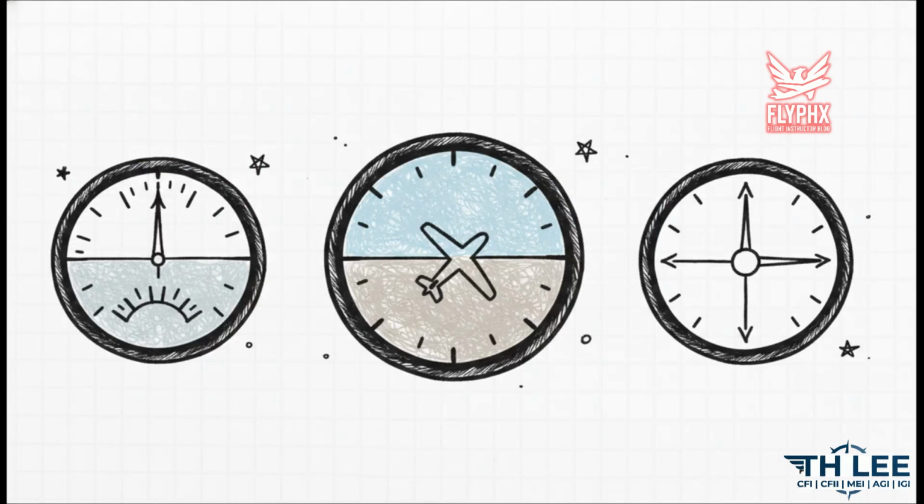Regardless of whether you are flying with old-school analog dials or a high-tech digital glass panel, every single instrument falls strictly into one of three categories: performance, control, and navigation. Performance instruments like your altimeter, airspeed indicator, and vertical speed indicator show the actual performance of the aircraft. Control instruments, most notably the attitude indicator, display immediate attitude and power changes.